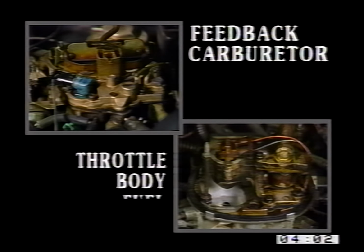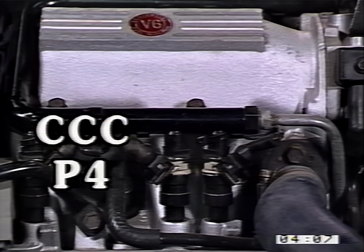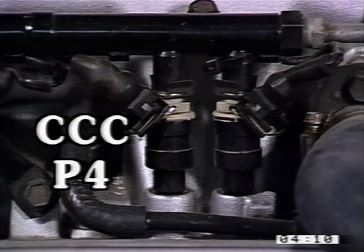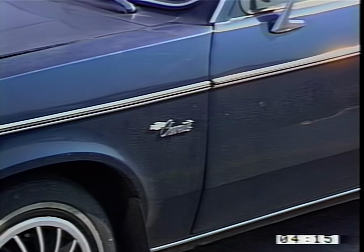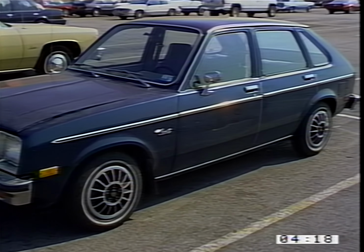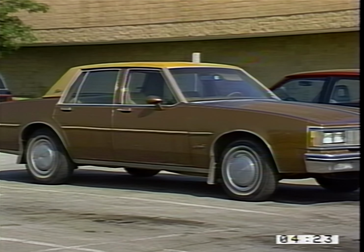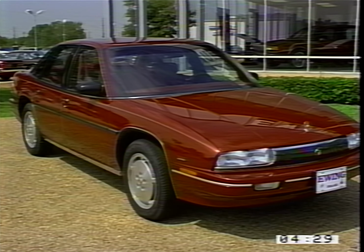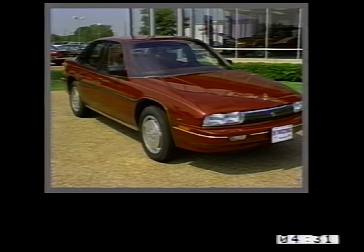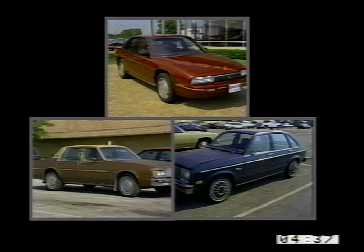The full-function C3 system is used with both feedback carburetor and throttle body fuel injection. The C3P4 produced later is a faster version used in throttle body fuel injection applications. There are variations to the C3 systems, including the Mini-T, a limited application fuel control design found on early economy cars, the 82 and 83 Olds LC variation, and the late model GM30 integrated ECM-BCM configuration. All of these designs are different, but on the whole operate and diagnose using procedures similar to those covered in this video.